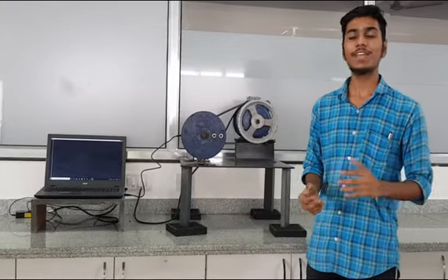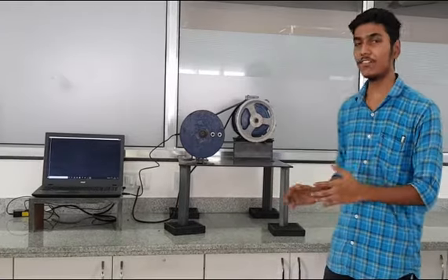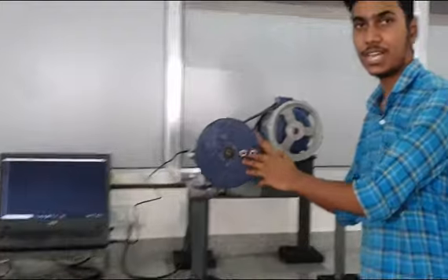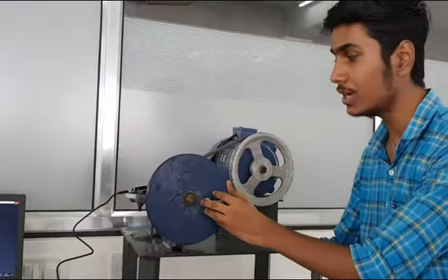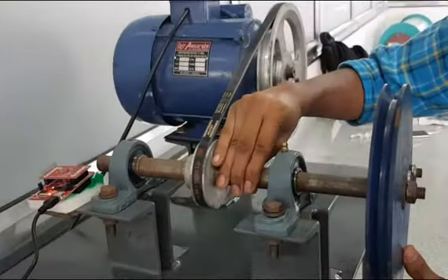Now the demonstration. Let's see how the AI code will predict the condition of a dynamic system. This is the testing setup that we have designed, and we have added some defects purposefully. The defects added are the mass imbalance condition, as we have added these screws on one side of the load. The second defect is looseness of the nut bolt, which will create an effect of misalignment of a shaft.